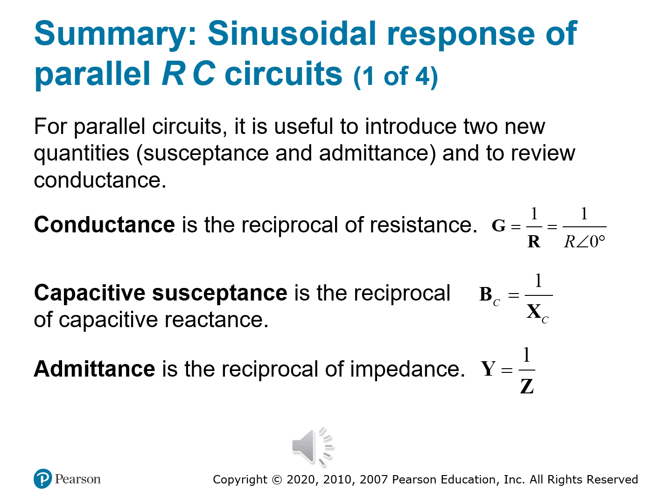So remember in the series circuit, we work with the capacitive reactance to model inertia of capacitors against alternating current. In parallel, we flip that relationship literally, and we work in terms of how easily the capacitor admits current, right? That leads us to admittance, denoted by capital Y. And admittance is just the reciprocal of impedance. So we look at the formula, Y is equal to 1 over Z. So admittance is equal to 1 divided by impedance.